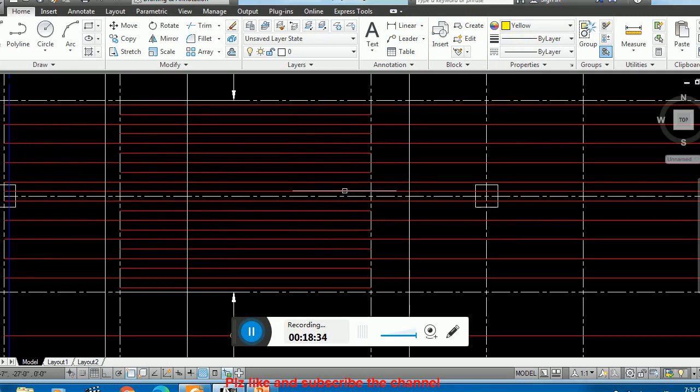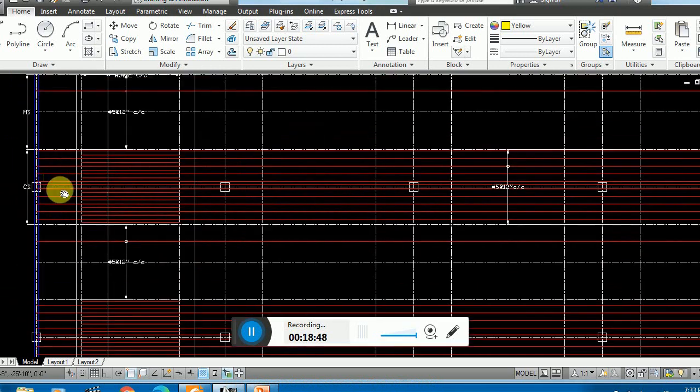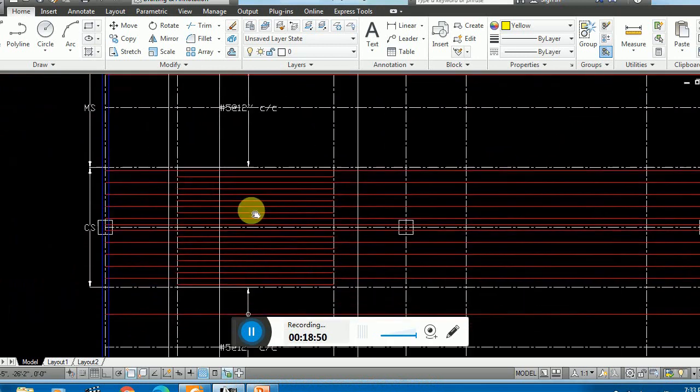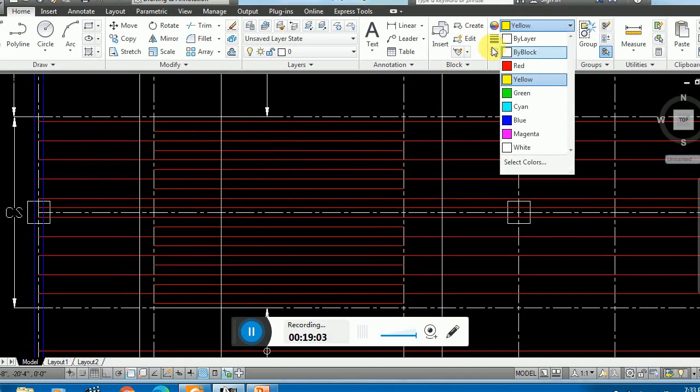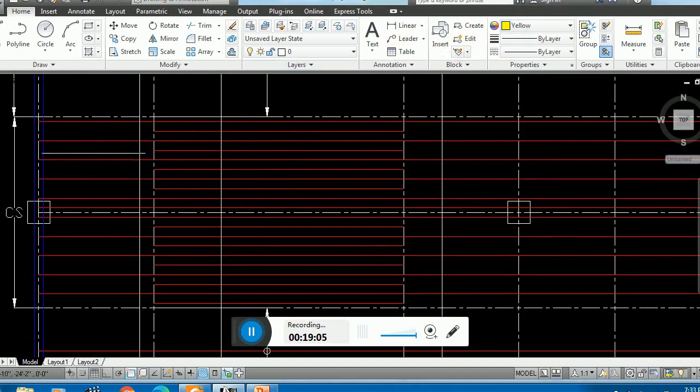And the positive movement in this region, which is the middle strip region, is 17 kip. Okay, and similarly here we don't need more, so I'm providing that amount of steel. Although here I can use number 5 at the rate of 8 in center to center, and here the bar you see, this is 12 in center to center. Let me check it. Yes, 1 foot or 12 inches center to center.